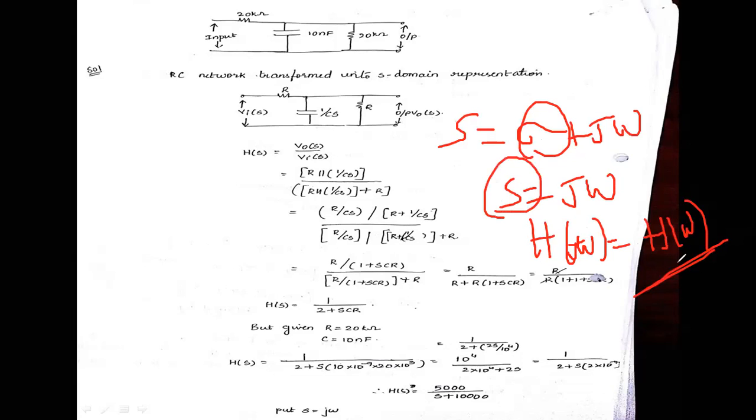Actually, S in the Laplace transformation is sigma plus j omega, my dear students. Sigma is a real function. There is no point on the real axis, so we get S is equal to j omega 1, meaning H of j omega. The shortcut notation is H of omega 1, the frequency. S is also the frequency, but it is in the form of sigma plus j omega, the real term and the imaginary term also.